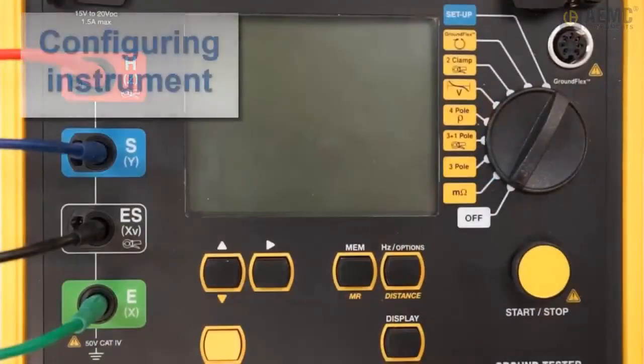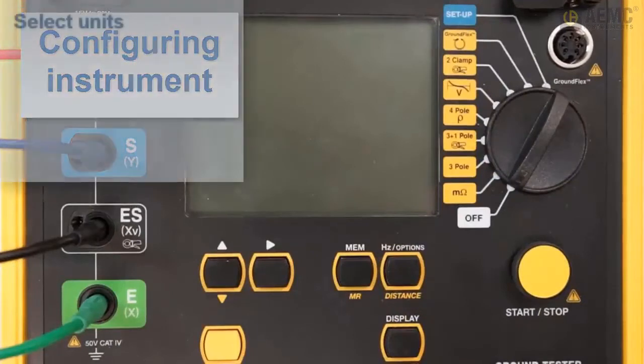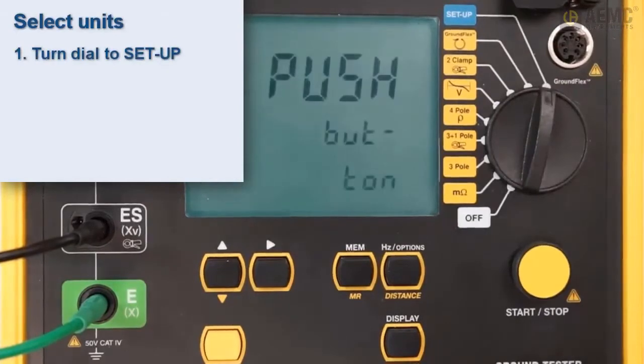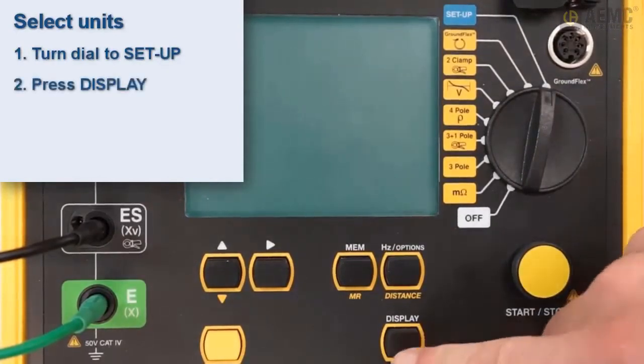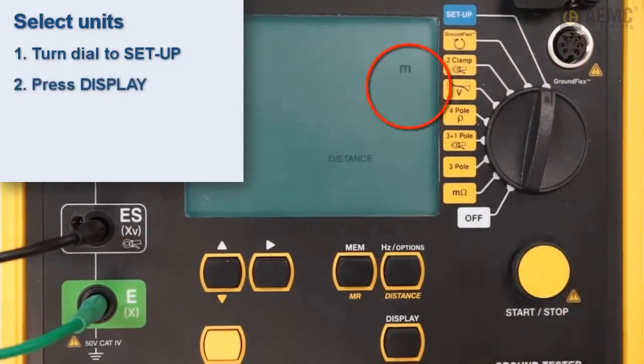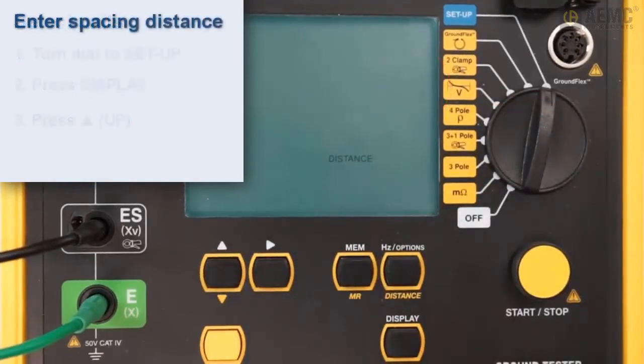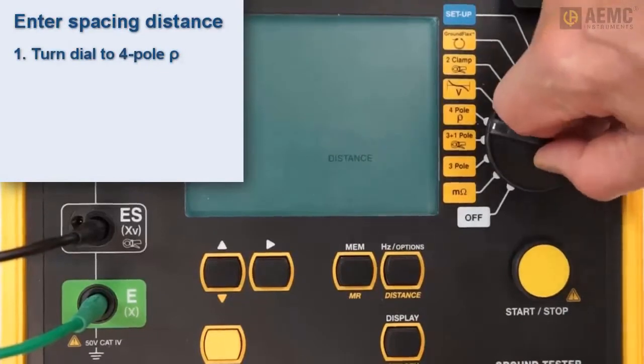To enable the instrument to accurately calculate soil resistivity, we must enter the electrode spacing distance. We start by ensuring the instrument is configured for the correct units of measure. Turn the instrument's dial to the setup setting. Then press the display button. The units of measure, either meters or feet, appear blinking on the screen. Pressing the up button toggles between these 2 options. In our example, we're using feet, so if this is set to meters, press the up button to change this setting. Next, turn the dial to the 4-pole rho setting.